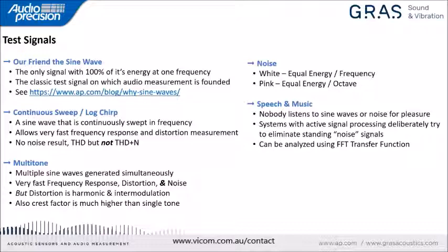One disadvantage of this technique that comes from the mathematical algorithm that underlies it is there's no noise result. So we can capture the fundamental frequency response and we can capture the distortion of the device, but we don't capture the THD plus N.